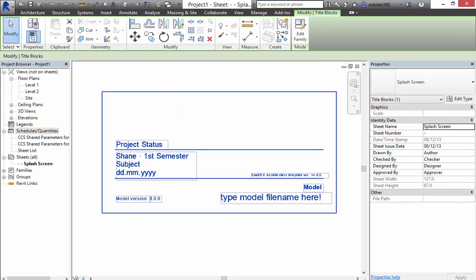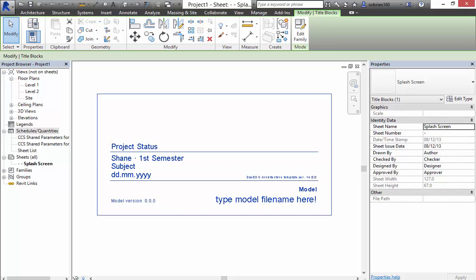So that updates the title block here, but it's not just on this page here, it updates it in the entire project. So that means every time you set up a new sheet, the client name and the project name are automatically there. You don't have to repeat work, and that's the big benefit of this software, is that you should only have to fill in information in one place, and it's repeated automatically through the scheme, if you're doing it right, that is.